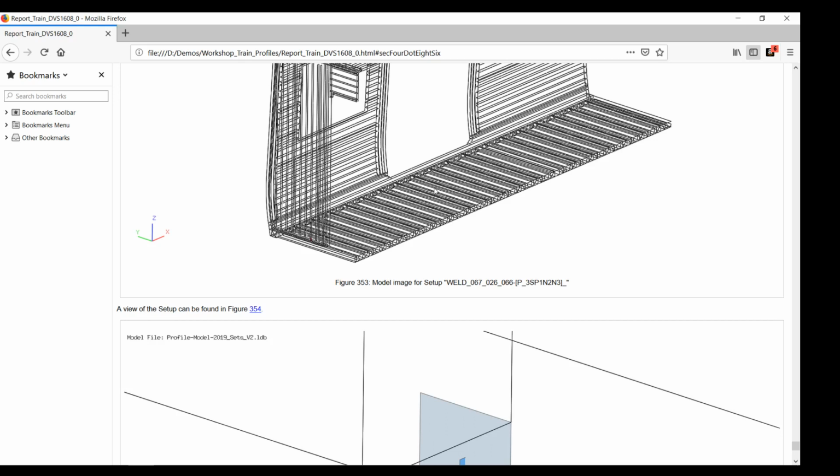I think especially the auto creation in combination with the topology filtering, and the new predefined weld settings are very useful, especially for a first quick approach or first quick assessment of the structure, and using these color status views.